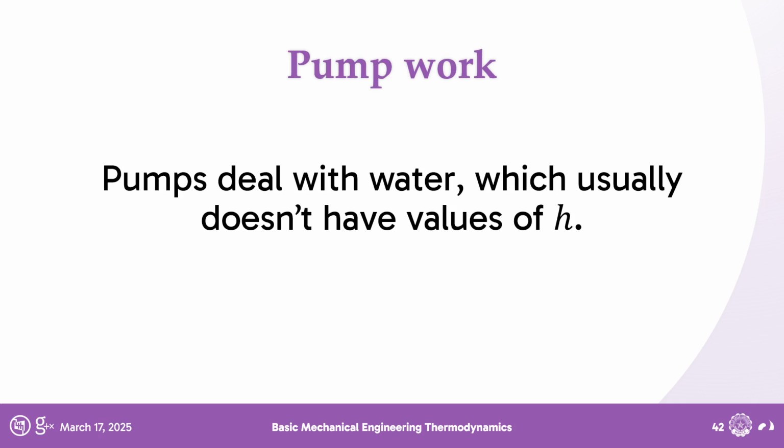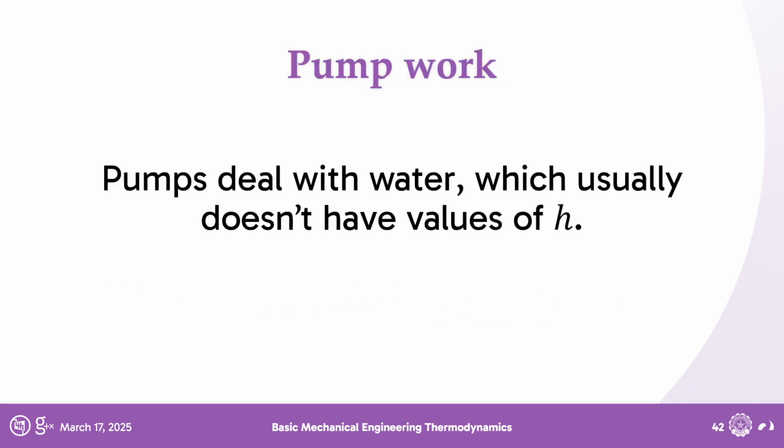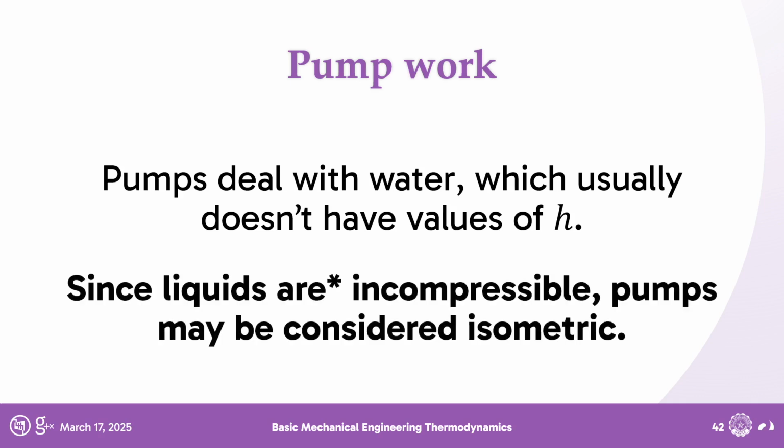And so how are we going to create a value for the delta H in here? Well, we're going to recognize that if it's liquid water we're talking about, we can leverage the fact that for this subject, we assume liquids to be incompressible.